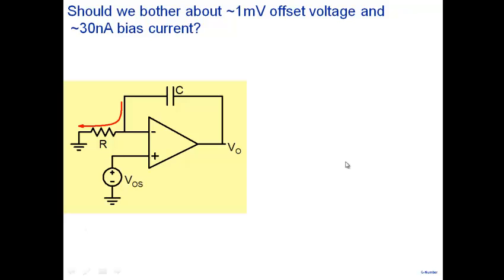For example, I said this is an integrator, RC. If I try to build an integrator using an ideal op-amp, this is what I would build. Now, note, I have not applied any input here, but we know that at the positive terminal I have an input offset voltage. Think of it as if there is a voltage applied to your op-amp, even if you don't apply anything here.